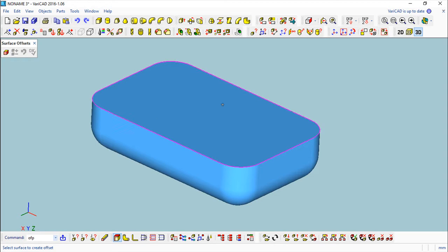I need to choose now which surface is going to be open. I want to open this solid on the top, so I will choose this option to select all except the detected one, and the selection is for making the thickness. You see it chooses everything with the exception of this one.